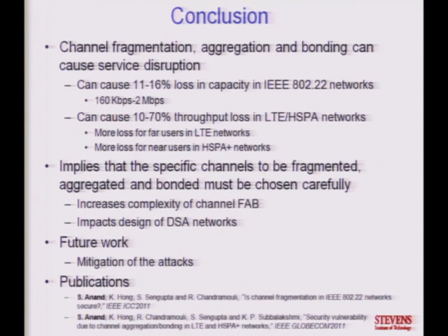So this correlation depends not only on the frequency partitioning, but also on the filters and other factors. It depends on the filters, the properties of the cyclic prefix, the frequency partitioning, and certain other parameters. Like some of them use equalizers and all that. It's a function of everything. So the correlation is not a simple inner product.